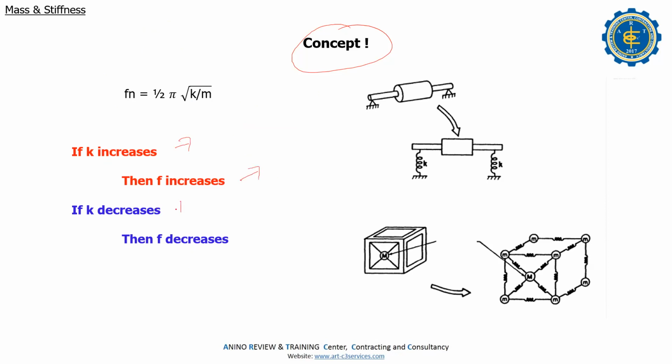If K decreases, the frequency also decreases. So if you have a critical speed, you have to compute how much weight you must remove or add to move away from the critical speed or frequency, because that is what causes this high vibration. Take note, maybe in the future you will encounter it if the time comes that you go to a startup.